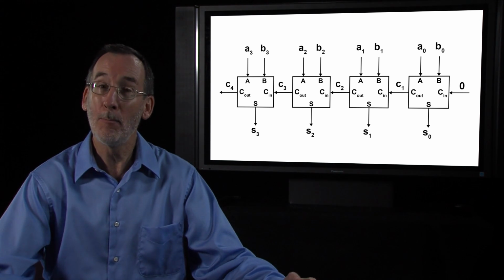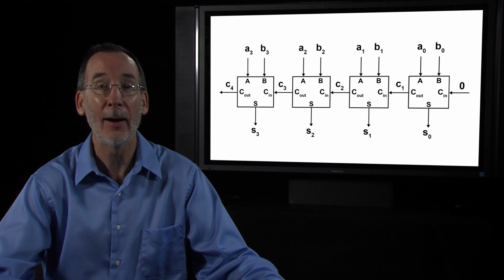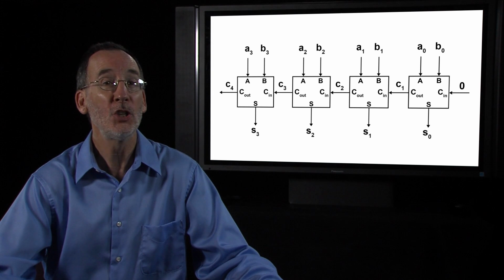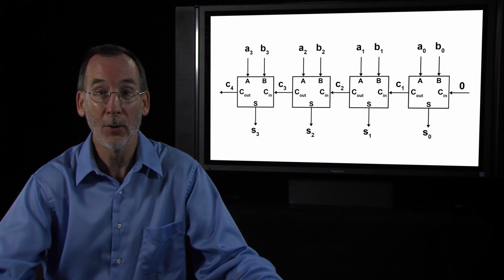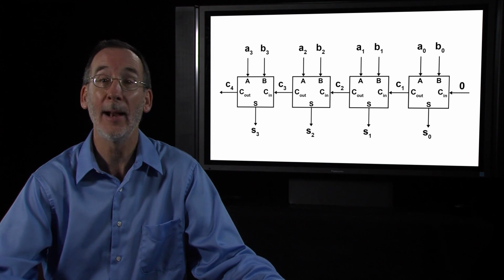So we can do this modular type of design where we take one simple circuit, this 1-bit adder that we've created, and we can just chain it together in this manner in order to create an arbitrarily length of adder. We can make a 32-bit adder the same way.